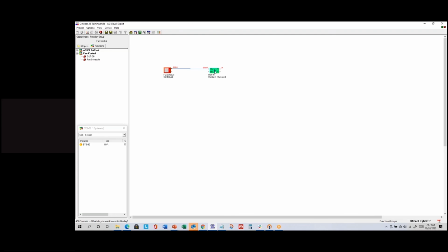Yes. Okay, good. In terms of the lines between the controllers, you don't have any direct control. You can't change where the line breaks. It kind of just breaks halfway in between. You can reposition your icons in such a way to get the appearance that you want. And then you can use the arrow keys on your keyboard to move the icon 1 pixel in any direction. So if you want to get that line perfectly straight, you should be able to.